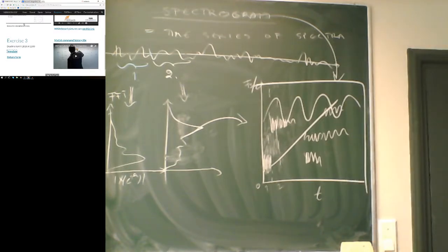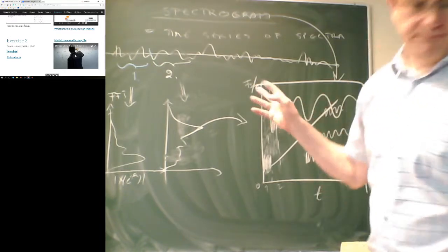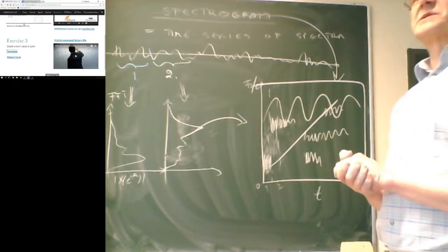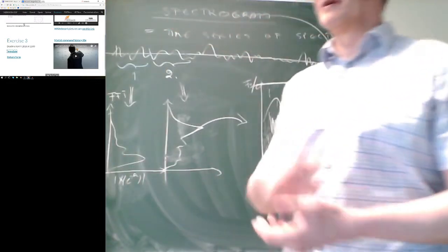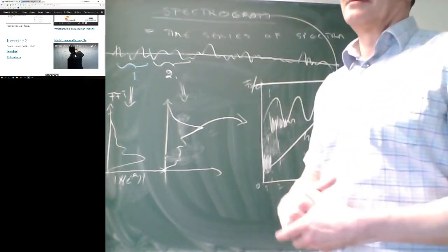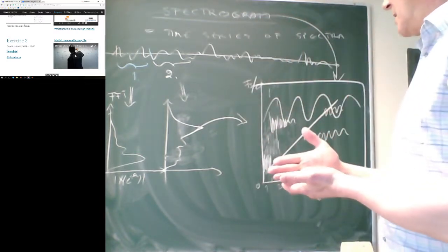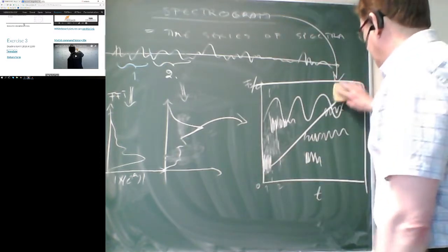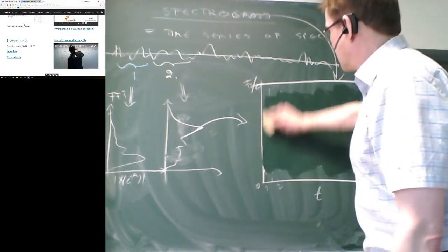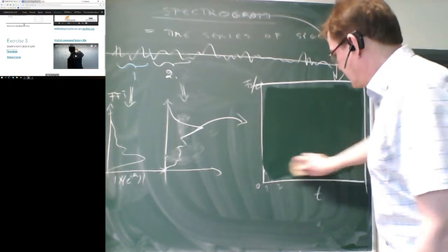And by the way, when you're doing the spectrogram, you can then also start doing some other kind of analysis like speech recognition. Speech recognition cannot be done simply in the time domain. You also have to have some sort of spectral information there, because you need to recognize different vowels and consonants, and that actually comes from the spectral image.